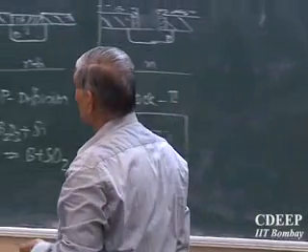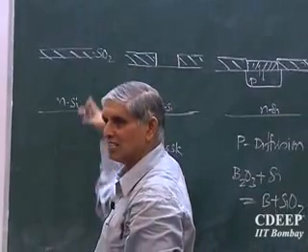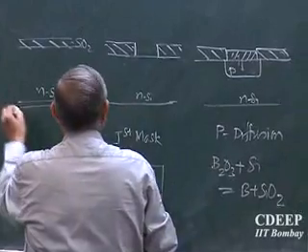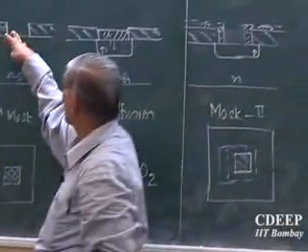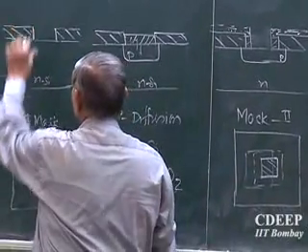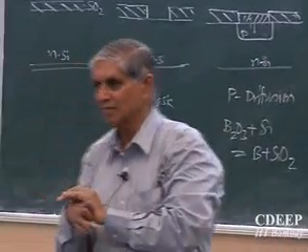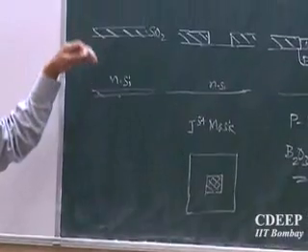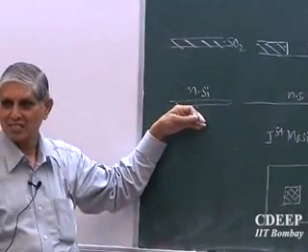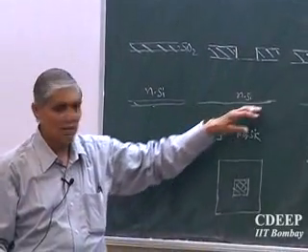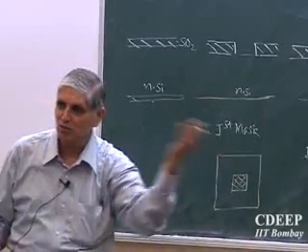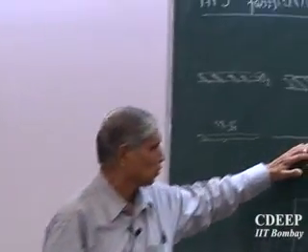One interesting feature I am never showing you, but remember, silicon is not selective. If the top surface is getting oxidized, at the same time the lower one will also get oxidized. However, when I etch this, that will etch away automatically, the whole wafer will get backside etching. So I don't show you. If this oxide is etched, the same oxide will come here. When I etch this oxide, the lower one will also go, because there is no mask there. I repeat. When I grow this oxide, silicon cannot say I will only have top layer oxidation; it happens on both sides. When I open a window for this, I will etch this oxide by masking. When I am etching this oxide, the lower portion is not masked, so when this oxide goes, the lower one will also go. So lower portions we never show, but actually everything that happens on the top happens on the bottom also.